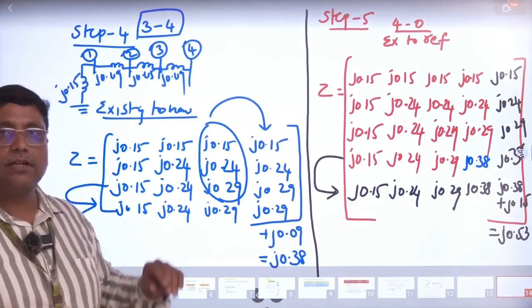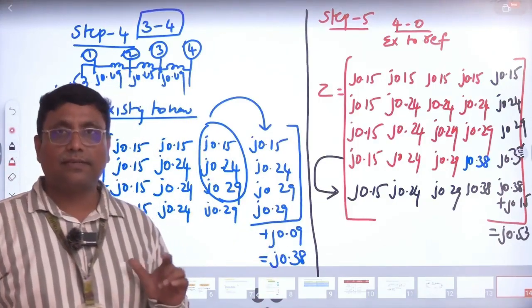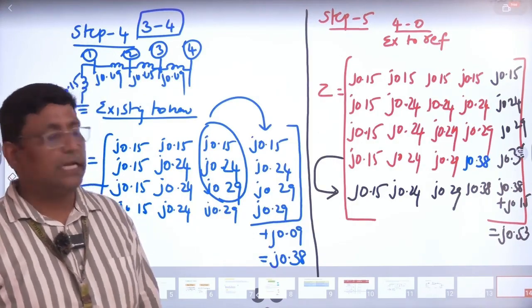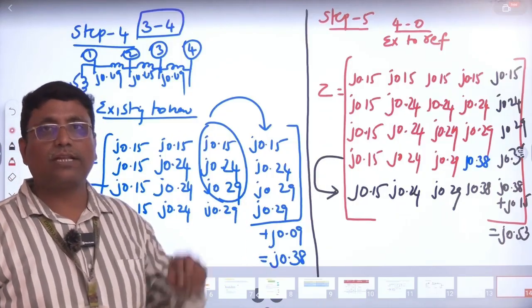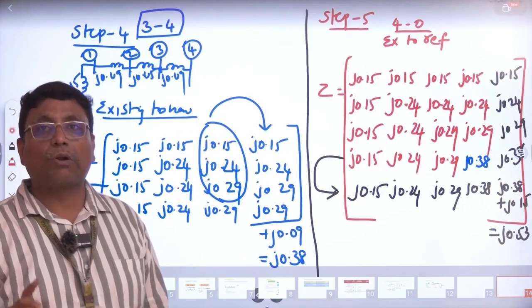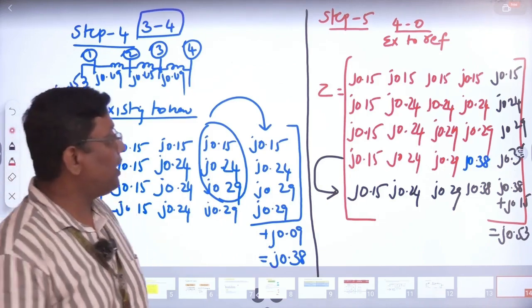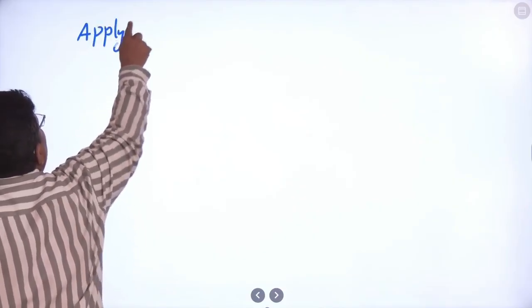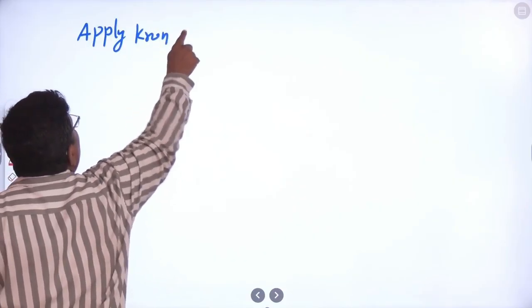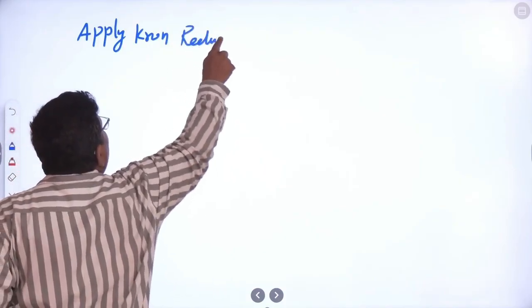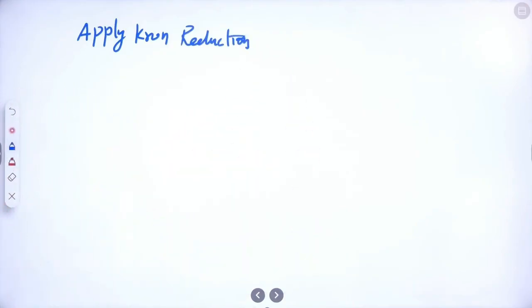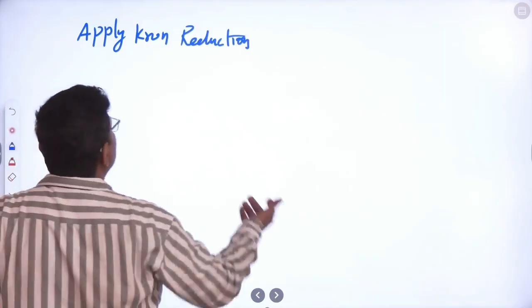But this is not the original size of the Z bus because it was formed based on the virtual node. So eliminate the last row and last column using the Kron reduction technique. The purpose of Kron reduction is to eliminate the last row and last column, because the last column was created by the virtual node.